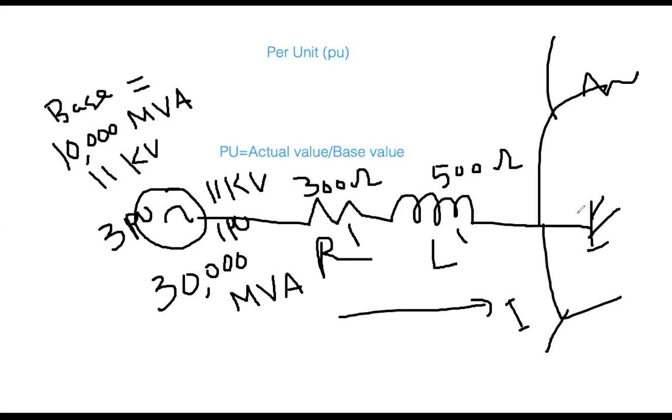And once you get the number, for example, you are trying to find the power of this branch and you got the result, okay, it is 3.2 per unit. I got this number after manipulating. So then what will be the actual value? Use this definition. Your actual value is the per unit multiplied by the base, or reference. Then at last you will get the actual value. But inside, you are able to deal with very small numbers. Those are called the per unit system.